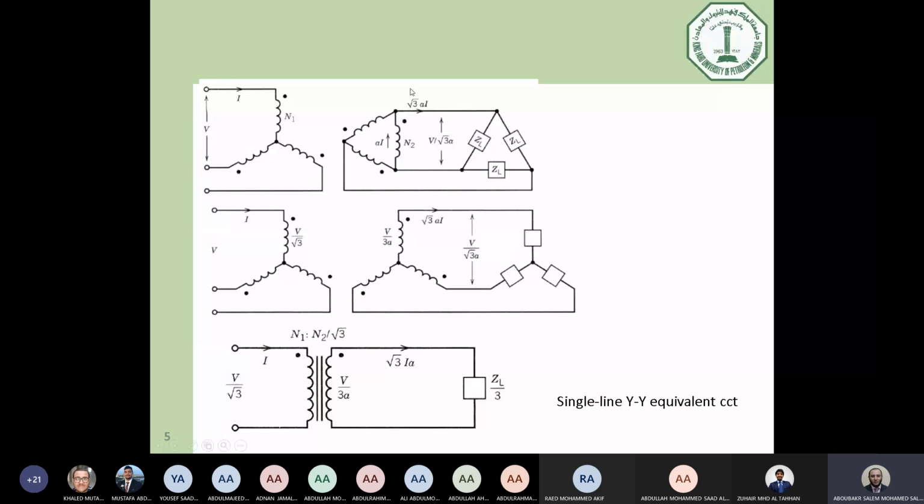So now if you make a black box here, just adding a box here, and you know now the line-to-line voltage, and you need to convert this black box into star connection. For sure, the line-to-line voltage has to be the same. We don't change anything in the circuit. We just virtually convert the delta into star.